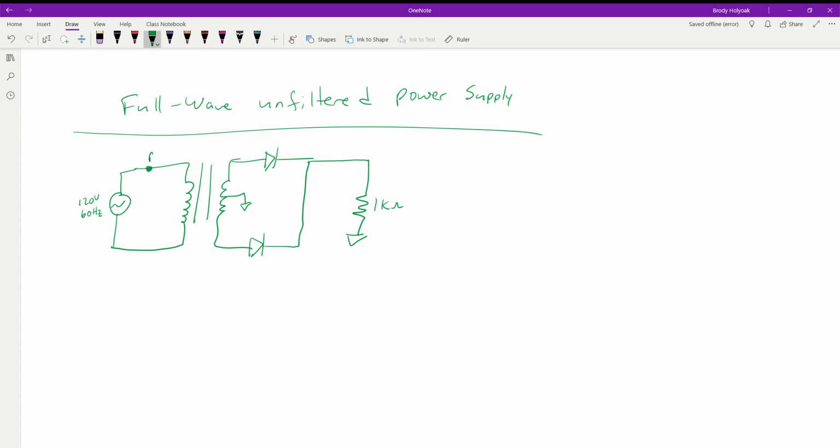So here at point A, this is going to be our primary. Again, we have 120 volts. It's not giving us an indication as far as what it is. It is an AC signal though, so we have to make the assumption that the 120 volts is RMS. We need to take the 120 volts RMS and convert it into at least a peak value, because that gives us options to see it on the scope, and that's honestly the easiest way to calculate and look at these: deal with AC signals by their peak values. Sometimes we'll have ranges, so we would give either a peak value or a max and a min value when solving these things.